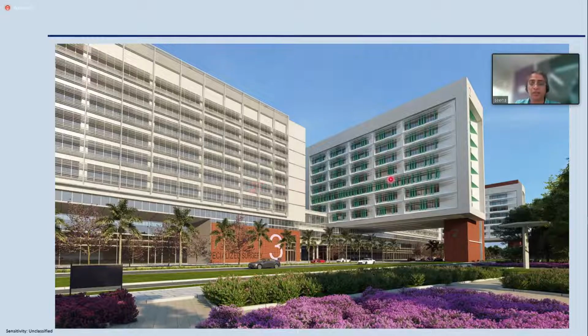So we got a line of buildings. We got a lot of facade skins here. What you see is terracotta. I see stone here, I see ACP here, I see some cute ACP verticals here. There is some glazing here. This is an aluminum trellis that I have in the facade. Again, I have a stick system here. So these are all the components. Now you can relate to what I took earlier. You start relating what you heard earlier to what you're seeing now.